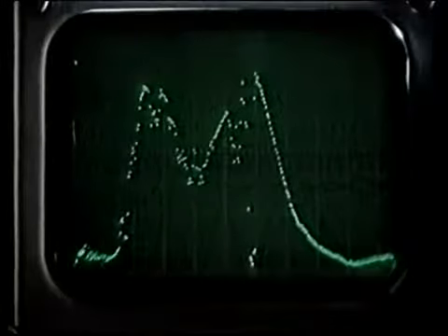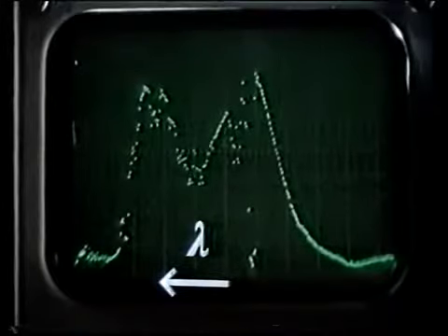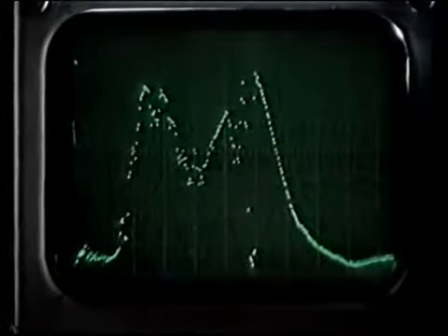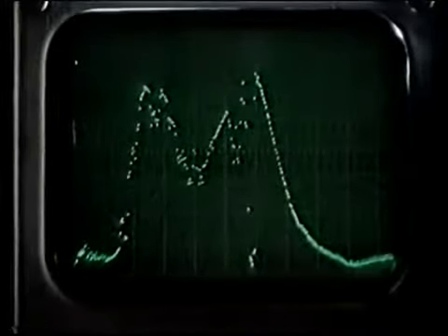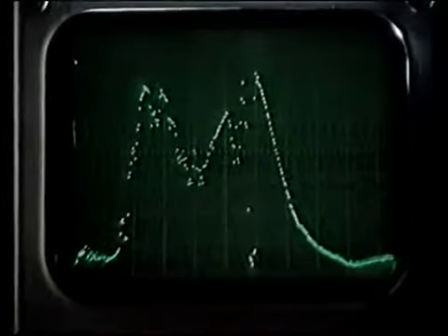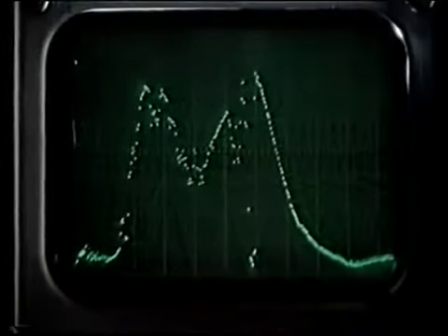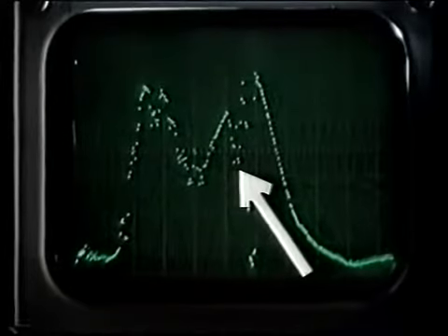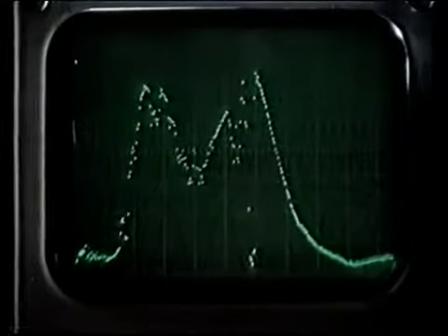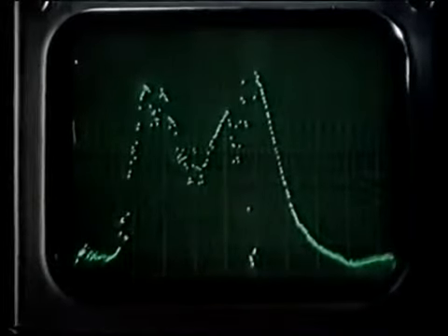And here we have the spectrum. Along the horizontal axis here, we're plotting wavelengths. Along the vertical axis, we're plotting intensity. That's the intensity of the radiation reaching our detector. Well, now, what does this tell us about the exhaust gases from the car? This trough here is actually due to absorption in our cell by carbon dioxide. It's at a wavelength around about 4.3 microns. This rather shallower little dimple here is due to carbon monoxide. It's at around 4.7 microns. And this generally depressed area over here is due to water vapor in the cell, somewhere in the region 6 to 8 microns.